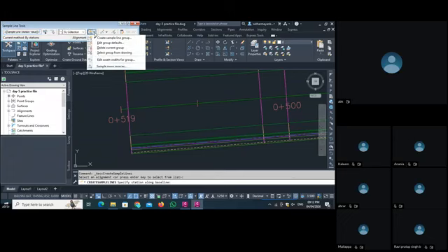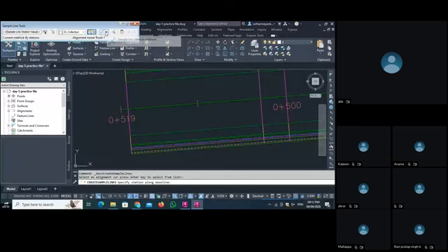If we click here, you can see create sample line in group. But before creating the sample line, we come here in this option, the sample line creation method. So first of all, we have to create the sample line. For that, there are lots of options. If I click at a station, at any particular station only, I create a sample line. From corridor station, the same way at 1 or 2 stations you can create. For each station you have to click.